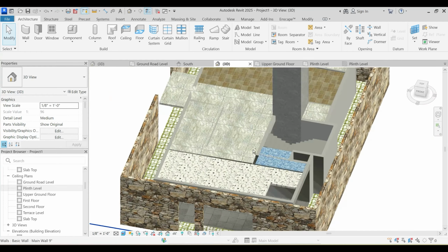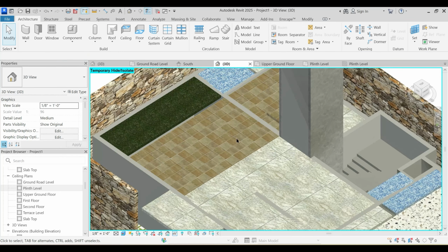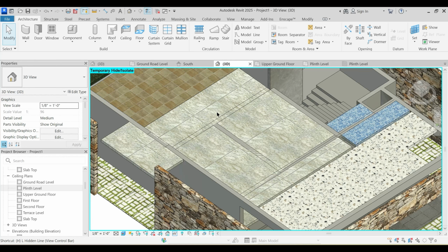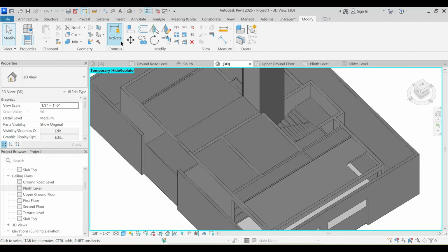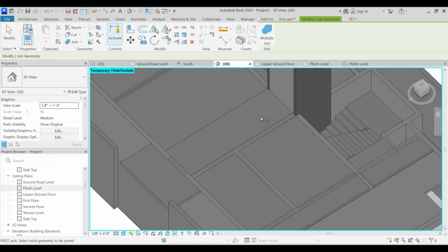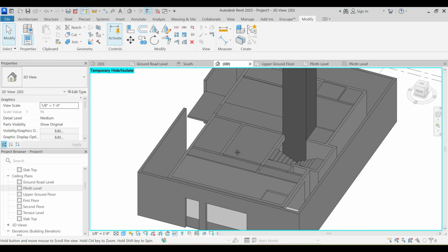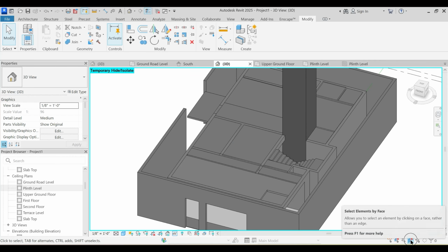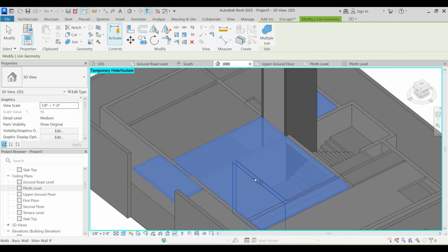3D. Yes. Okay. Now the required join condition, HH, and wherever required, you can see the walls over here. So HL, or let's say CC, consistent colors, the visual style too, consistent colors. And then I would just say modify and join. Why am I not able to select this particular floor plate? This option, select element by face, is turned off. So turn that on, say join and get rid of overlapping volumes. Yes.